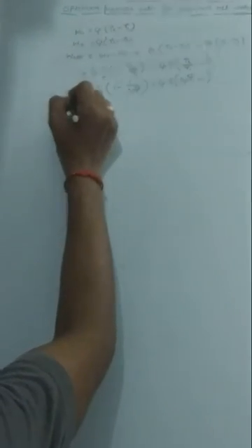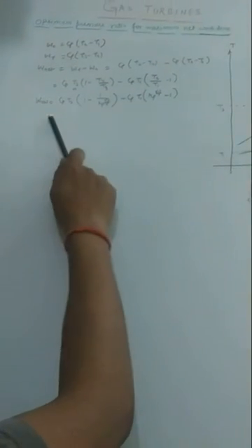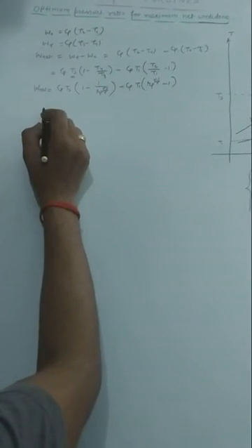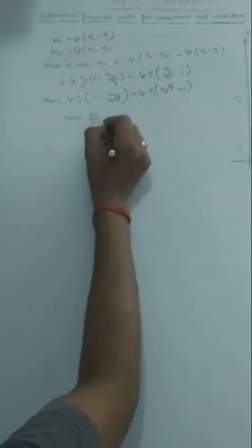This is the expression for net work done in terms of pressure ratio, because we are interested to find the condition for optimum pressure ratio. That's why we are writing the equation of W net in terms of pressure ratio. For simplicity, we can take gamma minus 1 over gamma as x. In the last stage, we can put the value of x in the expression as actual.